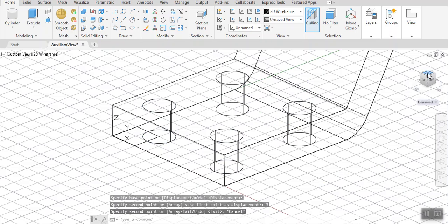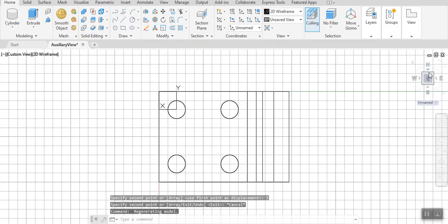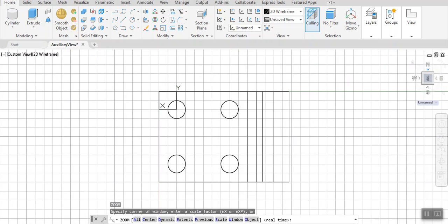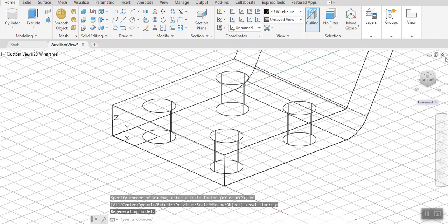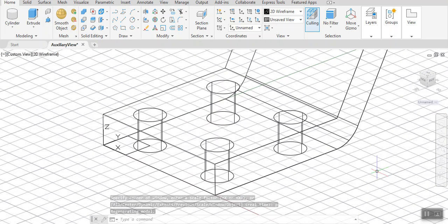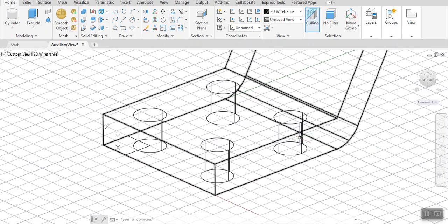And I want to show you the result. I mean, the result is like that. Okay? So zoom previous. Z, enter, P, enter. All right. You want to know what it looks like. I can subtract these. There's a subtract command, okay? And when you select a large object after the subtract command, enter, the small objects will be subtracted, and you're going to see the empty spaces. Okay.